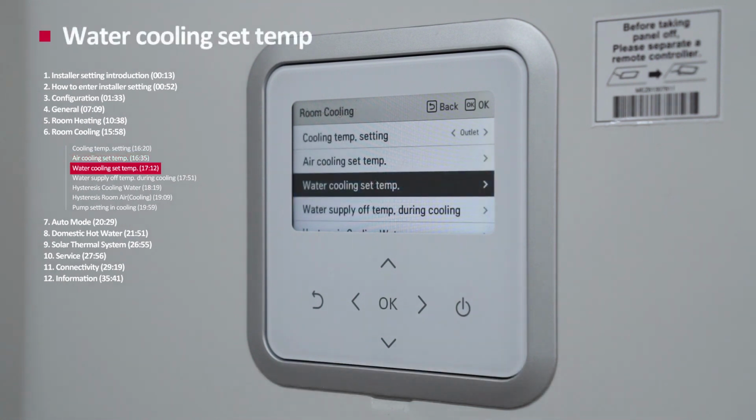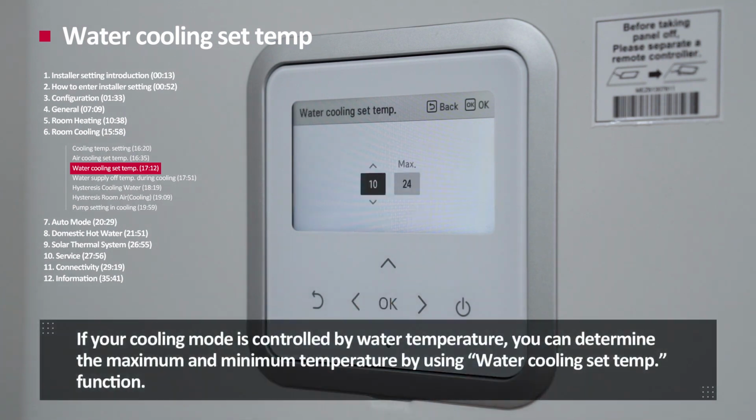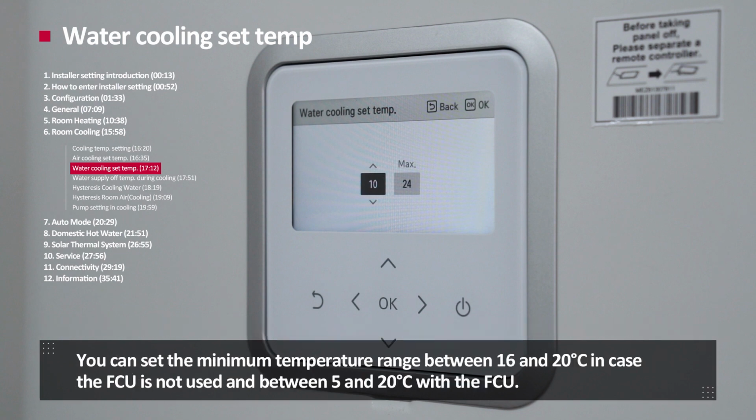Water cooling set temperature. If your cooling mode is controlled by water temperature, you can determine the maximum and minimum temperature by using water cooling set temperature function. You can set the minimum temperature range between 16 and 20 degrees Celsius in case the fan coil unit is not used, between 5 and 20 degrees Celsius with the fan coil unit.